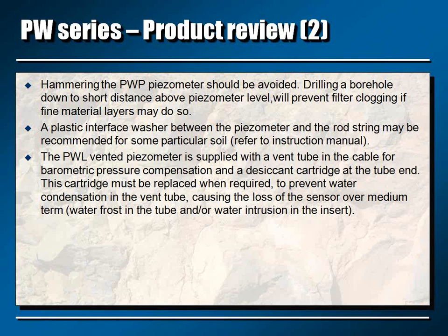Sometimes there will be some problem. For instance, if you leave the rod in place in soft material, sometimes there will be some settlement that will push the rods downward, and that will increase pressure. So this type of installation is interesting because it can be quick, but precautions must be taken when you are doing this installation.